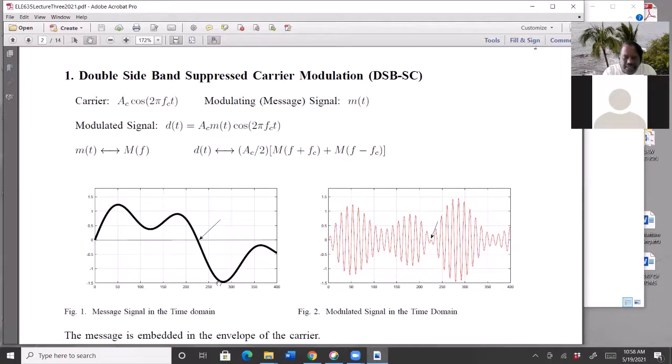Here, the audio signal is negative, but the envelope remains here, because what happens is this is negative. All that happens to the carrier signal is the carrier signal changes phase. So here everything is positive. A signal that is constant amplitude got modified according to this signal because you are multiplying by this. But at this moment, you begin to multiply by negative numbers. So this whole expression earlier, instantaneously, had a positive number.